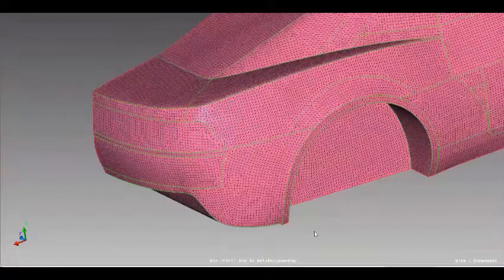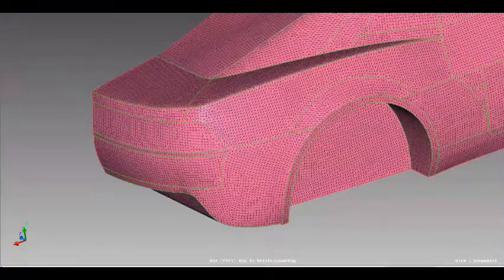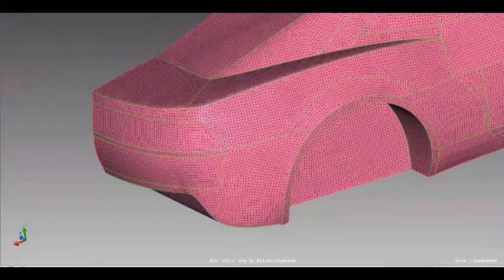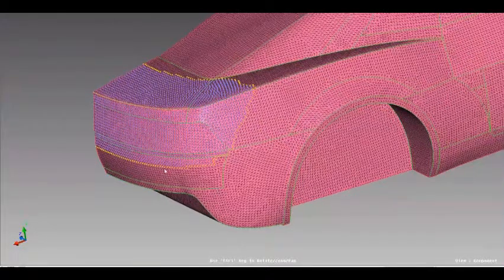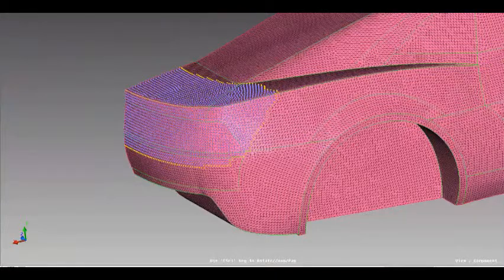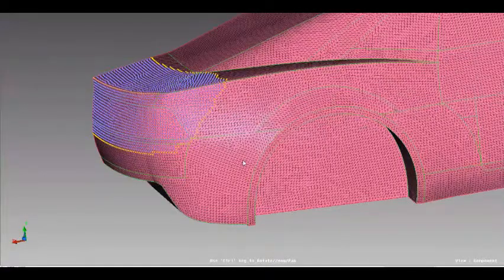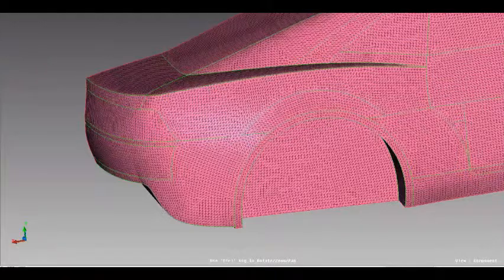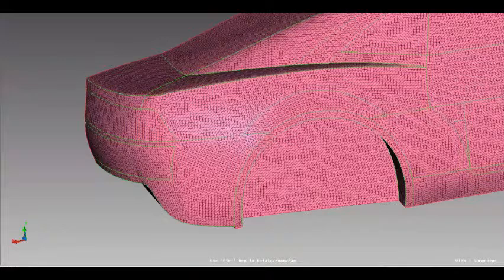So once the morph set is created, I need to link the morph set which is created to do the parametrical change. So once you click on link, MeshWorks automatically links the created morph set, which shows what are the control nodes and deformable nodes, fixed nodes, which are linked to the morph set. Then a user can either create a parameter using the parameterization tab, or a user can go for tools and do a one-time execution. So right now I'm going to use the tools, translate, and I'm going to select all my control nodes,